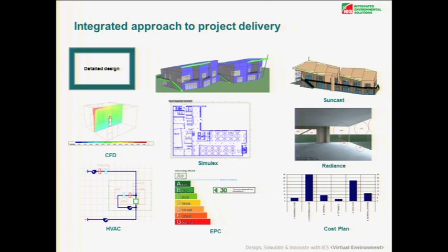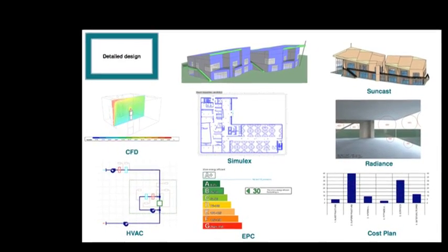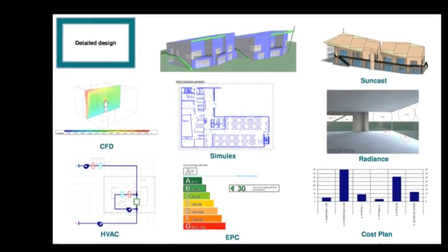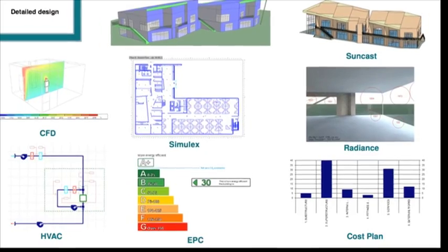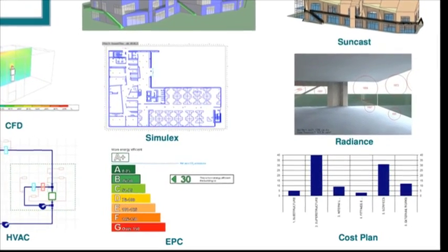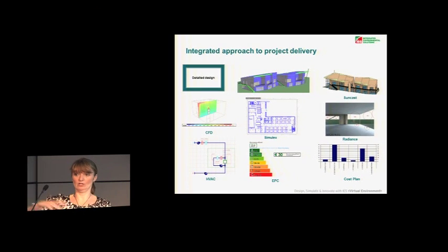And then in detailed design, really what we're talking about here is a submission quality model, okay? So the model that we're going to be using with all of the detail refined in it would then be submitted as part of your BREEAM certification or producing your Part L document, for example. But this introduces quite an interesting point in terms of the management of the BIM model. Because going through these slides here, it would look like it's just the same model that I'm taking in and then developing through those various stages. In reality, the workflow is more likely to be bringing a different BIM model in at different stages in the process. Typically, the architect will develop that and will be changing layouts and maybe changing shape and stuff like that of parts of the building, and then the engineer is bringing those new models across, if you like.